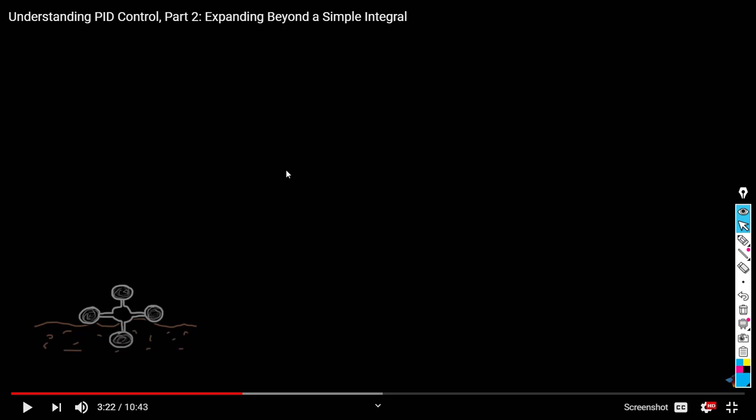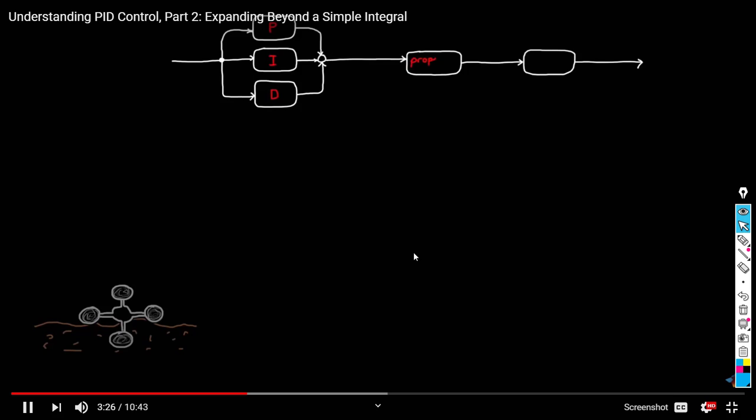The system will actually overshoot because of the integrator, which doesn't know that your actuator is saturated and keeps accumulating energy and sending commands to the system to eliminate the error. We're trying to control its altitude with a PID control law.